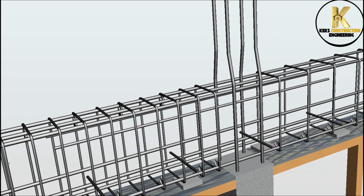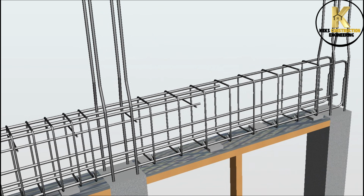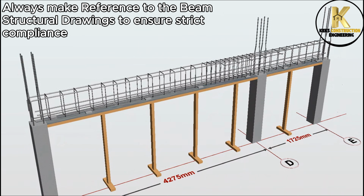In a case where there are more than 2 extra top bars at the second layer of the support, you can use short bars like this or smaller stirrups to tie and hold them in place. Always make reference to the beam structural drawings to ensure strict compliance.